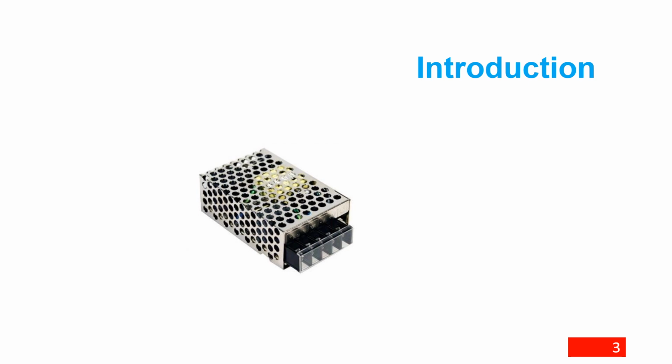The switch mode power supply is also known as power supply, supply unit, regulated power supply, etc. It is composed of a converter that converts electrical power efficiently using switching devices, and using storage components like inductors or capacitors to supply power when the switching device is in its non-conducting state or off state.